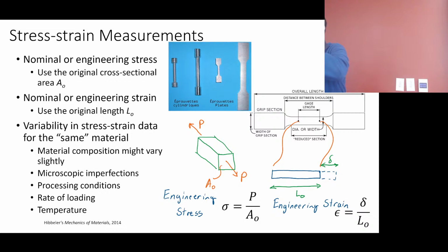Okay? And let's just say that there's noise in that voltage signal. If you're trying to measure 3 newtons, the 5 kilonewton load cell may just spit out noise that's going plus or minus 5, 10 newtons all the time. Whereas the 100 newton load cell would be able to give you a more stable readout and probably get you down to the 3 newtons.